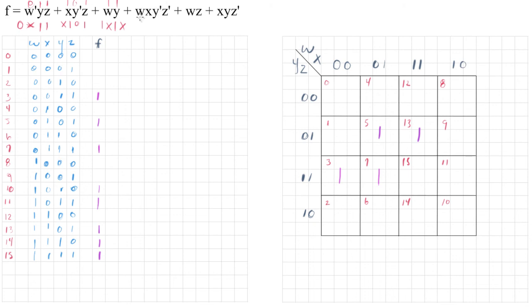This one's easy because we're not missing anything. On, off, off, right? On, off, off. That's what we're looking for here. 1, 1, 0, 0. So come down to 1, 1, 0, 0. And there it is. Mark that. I forgot to mark these on the K-map, but I'll go and do it afterward.